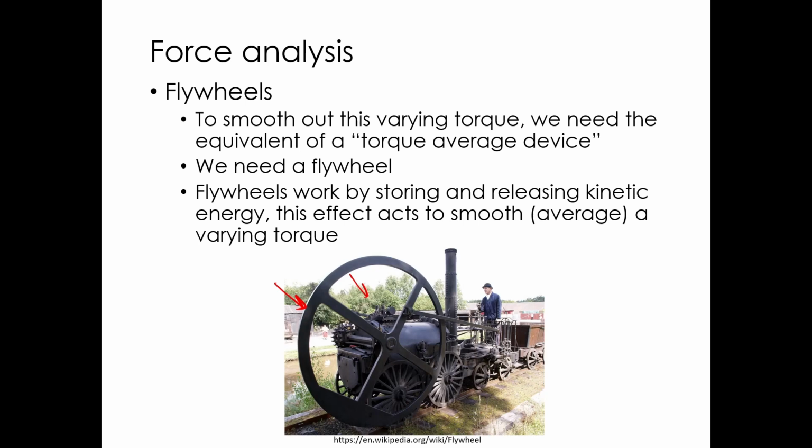The only time you actually get any work is from the power stroke. The other 3 strokes all require work, and you need some place to store energy from the power stroke for those other strokes. And that's the flywheel, the mass of the vehicle it's connected to. Those things all are part of that system.